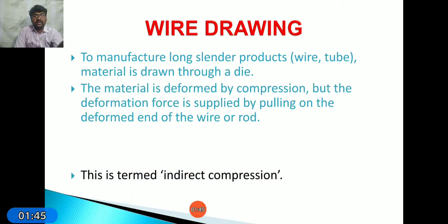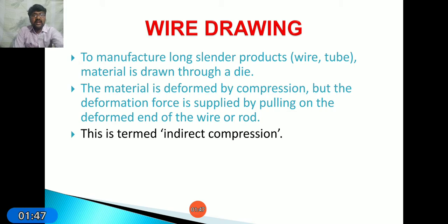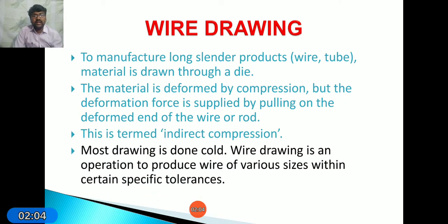It is termed indirect compression because we are applying a tensile force on the workpiece, but the type of force acting on the material is compressive. So it is called the indirect compression method. Most drawing is done cold.